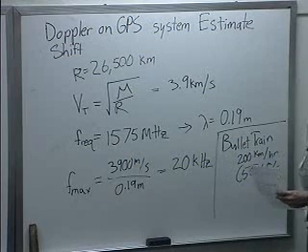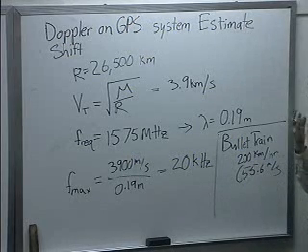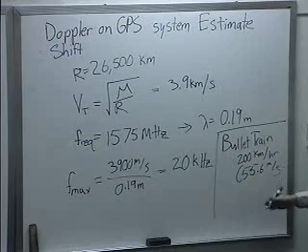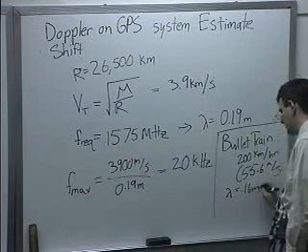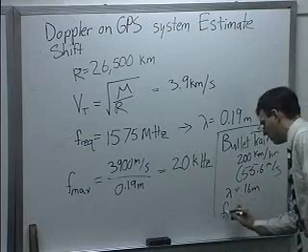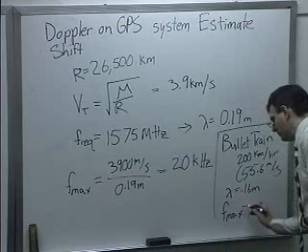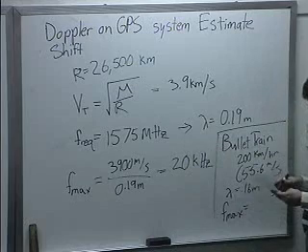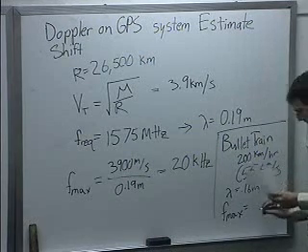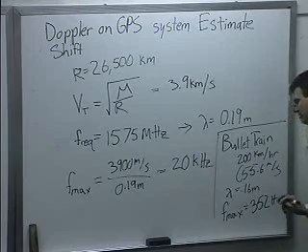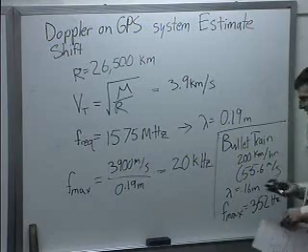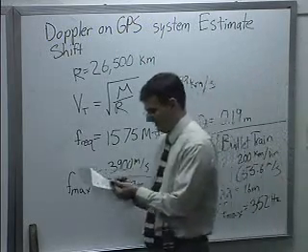The frequency is a little bit higher than GPS, so the wavelength is a little bit smaller. Wavelength is about 0.16 meters. But our maximum Doppler frequency, if we calculate with the same formula, is going to be about 352 hertz. Much, much smaller than it could potentially be on a satellite.